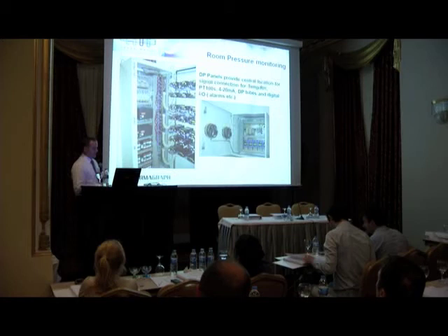Now obviously, when you measure pressures, one of the things you do is you put a delay on it, because if you're measuring the differential pressure between adjacent rooms, every time someone opens a door, it's going to go into alarm. So you allow 90 seconds or 2 minutes for people to walk through doors, and that's tunable. What we often find with facilities is we set the limits from day one, and then we go back in a few weeks, find out how they're getting on, and fine tune it.